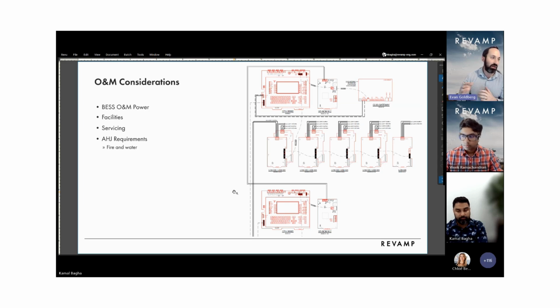In that case, you need to look at power. Is it going to be 480 volt or 208 three-phase? If it is, it's likely not going to be already at your substation. So you'll need to consider if you have to bring in another circuit, or maybe if it is 240 volt that they need single phase, do you have enough capacity on your station service transformer?